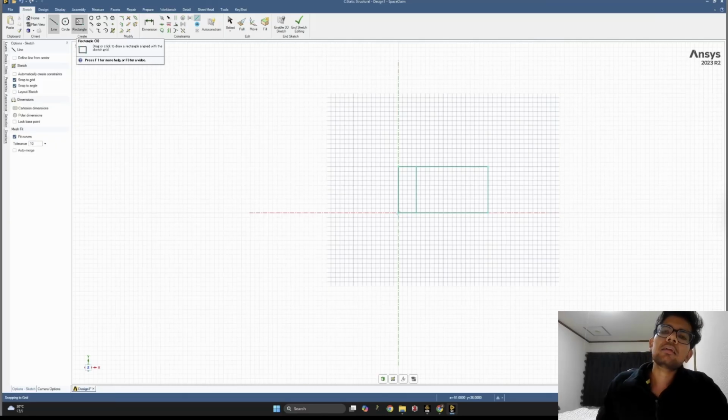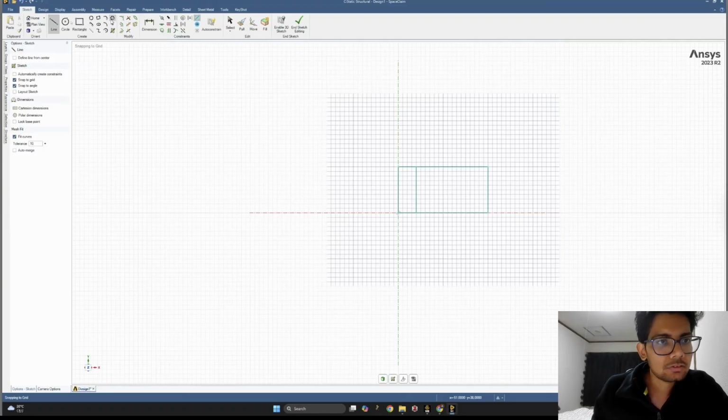And the other thing in CAD designing is you can't be so inaccurate, or you cannot do approximate placement of the lines or rectangles. So the other useful thing to know is the shift key, which will help you to find out the distance from one of the reference edges. Suppose you want to create a line which is 15 millimeters away from this point.